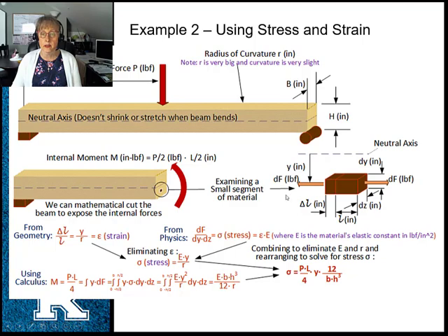This comes from the talk about Timoshenko, but modulus of elasticity was essential in Timoshenko's working of calculus to find an equation that we could use to design beams. He has a formula right here: stress equals strain times modulus of elasticity. Strain is really the deflection of something, the amount it stretches, if you will, divided by its initial length. Stress is the force on something divided by its cross-sectional area. So this really is F equals kx, same as for springs.